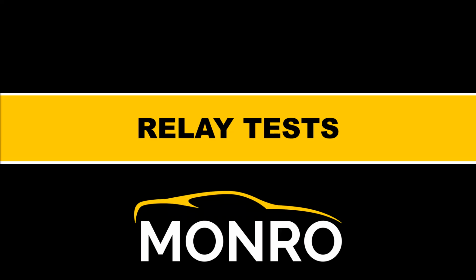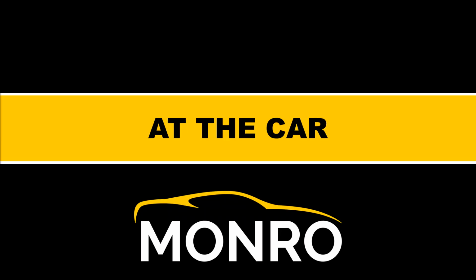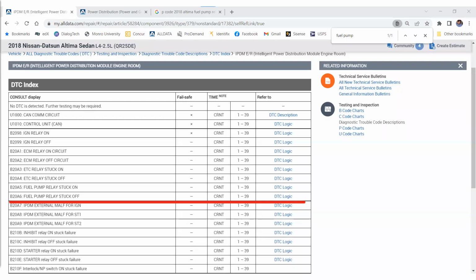Now that we've actually seen it outside of a car, let's talk about what it takes to do this actually in the car. Now, half the battle when it comes to doing diagnostic work and diagnostic testing is not the test itself. It's the preparation work that we really need to have going into it. We're going to be taking a look at a 2018 Nissan Altima that's got actually a code in the body control module for the IPDM, and that's an Intelligent Power Distribution Module. Big fancy term for a smart fuse block, but it basically says that the fuel pump relay is stuck off.